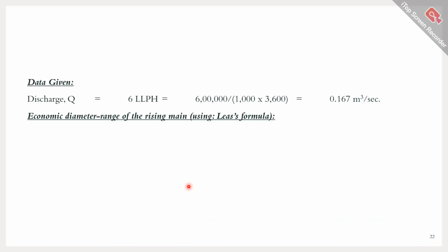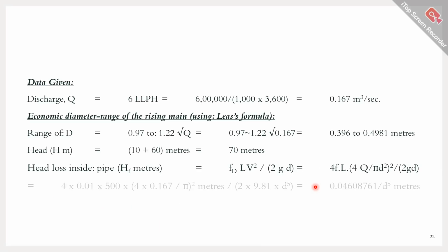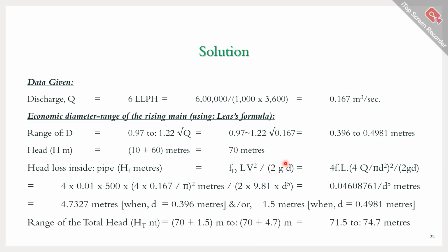This was the problem basically. We just calculated the pressure drop because of the frictional force that is present in between the fluid that is flowing through the pipe and the pipe wall. The formula is called the Darcy-Weisbach equation, that is given here. Frictional pressure drop equals to Fd into L V square, over 2 G D. V you calculated in terms of volumetric flow rate divided by the surface area, and the rest of the values are given.